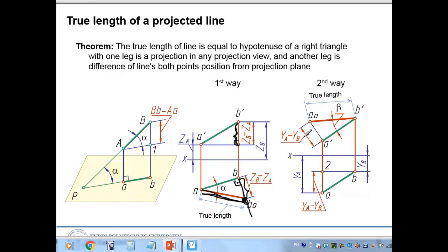The second way is the opposite: get this distance, make a straight line, and at either end of this line create a perpendicular line. Then put that distance there, define the A0 point, and connect this A0 point and the other end of the given projection line. So the red one is the true distance, the true length. Okay, so the way is like that.